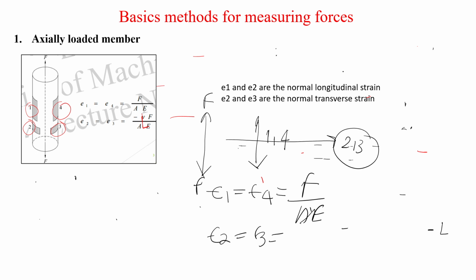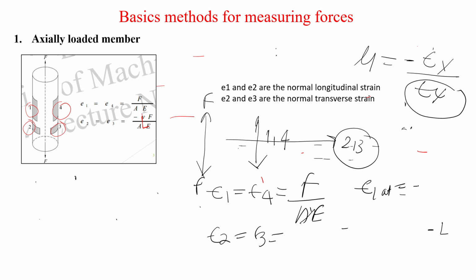So we know that the Poisson ratio is equal to minus of the lateral strain epsilon y upon longitudinal strain epsilon x. Sorry, I have written it opposite. It's the ratio of the lateral strain upon longitudinal strain. So this we know, the longitudinal. So the lateral strain can be found. So epsilon lateral is minus mu times epsilon longitudinal. This we can write.